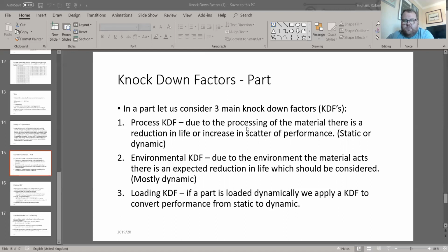So processing titanium is pretty difficult. You end up having to generate quite a lot of heat, and you also have to put a lot of force into it to get it to move or change shape. Aluminium, on the other hand, is really easy to work with. What you find is then, if you have to put a lot of mechanical effort and thermal effort into the part, if it was titanium versus aluminium, then there's potentially more knockdowns from processing on titanium than there is aluminium.